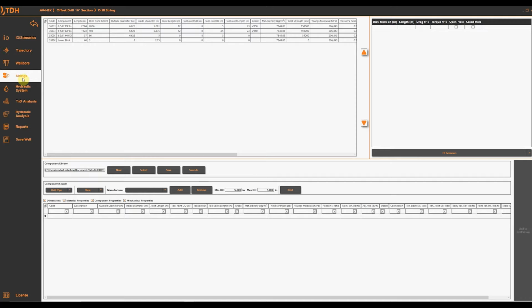The next thing to do is create a drill string, and that needs to be the drill string which was used to drill this particular well. I went back to the daily drilling report and came up with these 6 5/8-inch drill pipes, then heavyweight, and then a lower BHA. Based on the reports, this is what was used, these tool joints. For the lower BHA, we average all these IDs and the weight. We don't necessarily need to specify each sub, stabilizer, and other component. It's just one long drill collar with averaged IDs and weights.